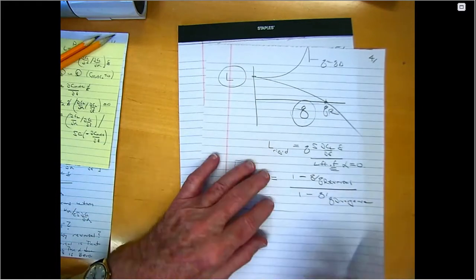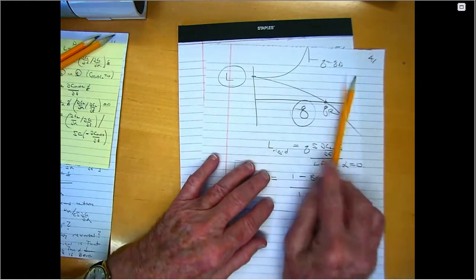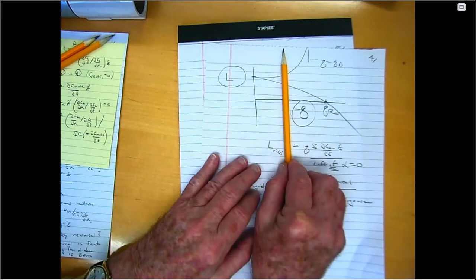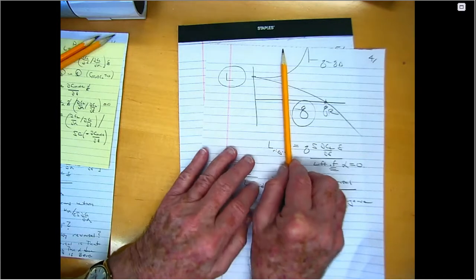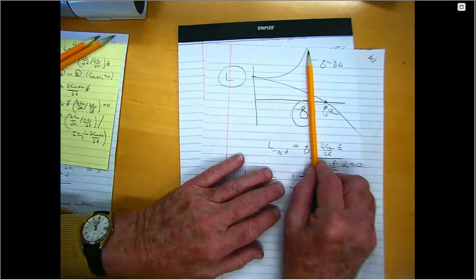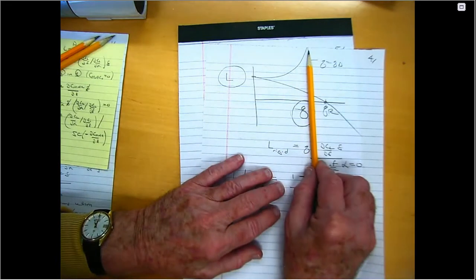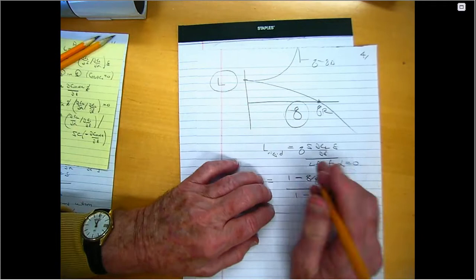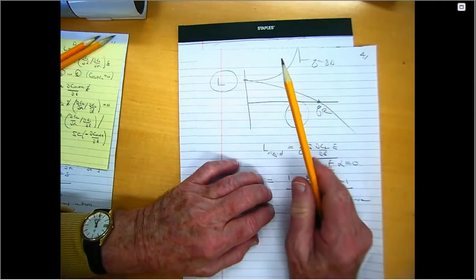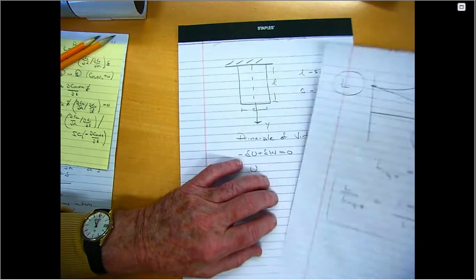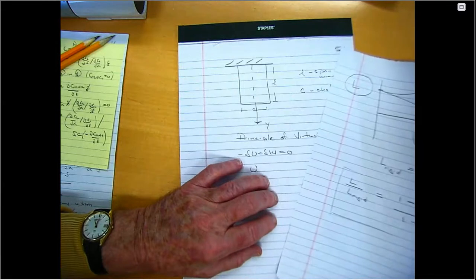So people might design a real airplane. People might say, I want to design one to reach the reversal condition. I'm not willing to allow this thing to fly on that pressure. Or conversely, if I come to that pressure or a higher one, I have to stiffen up the wing, right? If I stiffen up the wing, it probably makes it heavier, which makes it less desirable in other ways. So there's a penalty to do that. Okay?